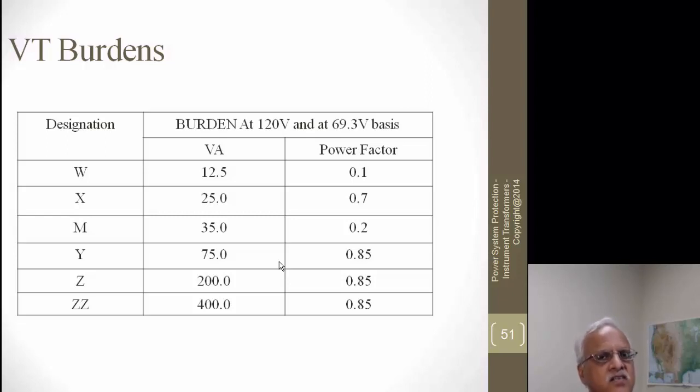They are very high ratios, and unlike power transformers, which have one or two ratio levels like 115 to 69, or 345 to 115, or 230 to 69, or 69 to 13.8 or much lower voltages, they don't go to 2,000 or 3,000 as we see in potential transformers. These voltage transformers or potential transformers, I keep interchanging these terms, they are the same.